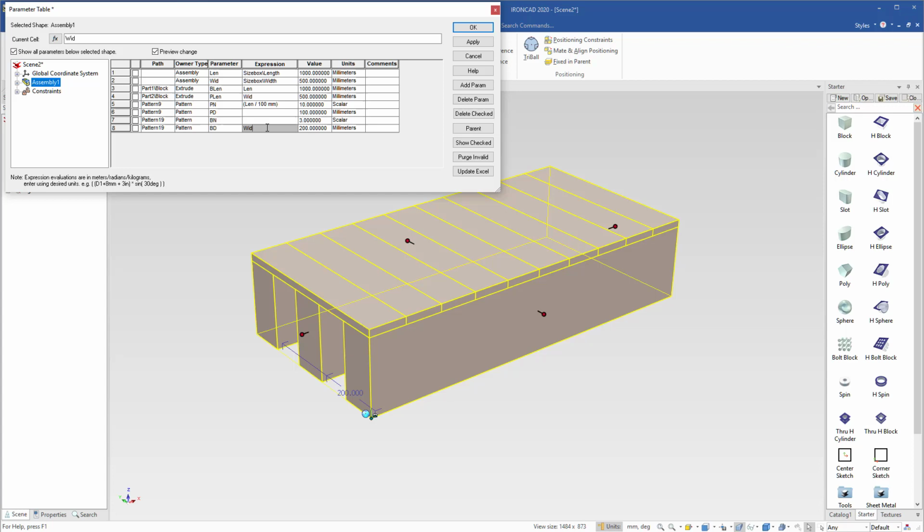So it's going to be the total width of whatever the width of this box is, minus the width of one of these boards, which in our case is 100 millimeters. And we're going to divide that whole thing. So we're going to put parentheses on both of these elements here, and I'm going to divide it by the total board number minus 1. And again, we'll put those in parentheses because we want that to do that as well. Just simple math. So we're going to subtract 1 from the board number, which gives us 2 boards, minus the total distance here, minus 1 of these boards will give us that calculation of 200. So if I click out of this, it should still be 200. So there we go. Okay, so we kind of set up our values here.